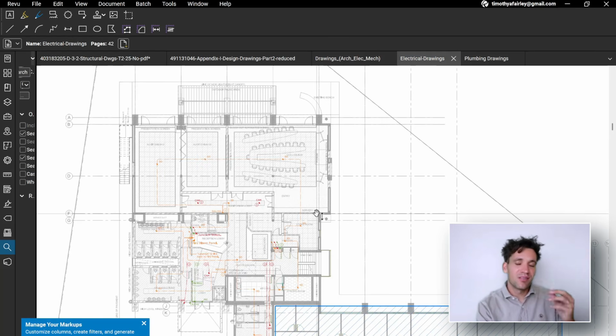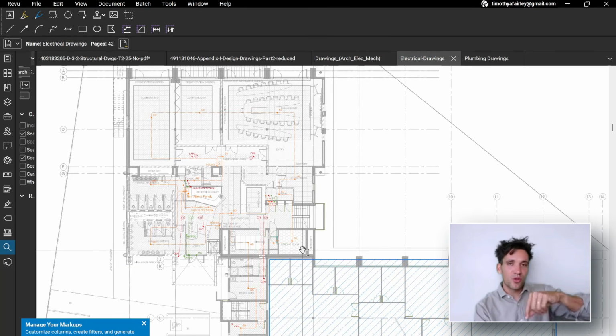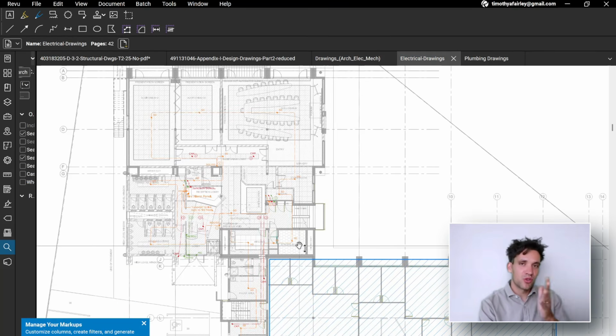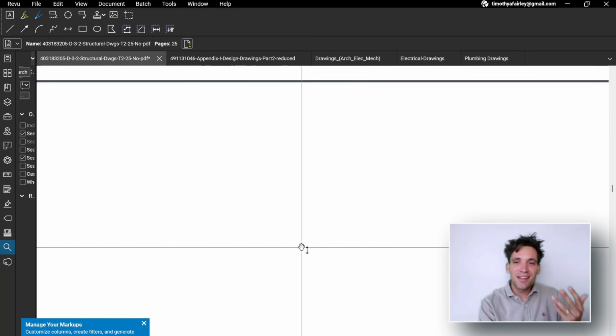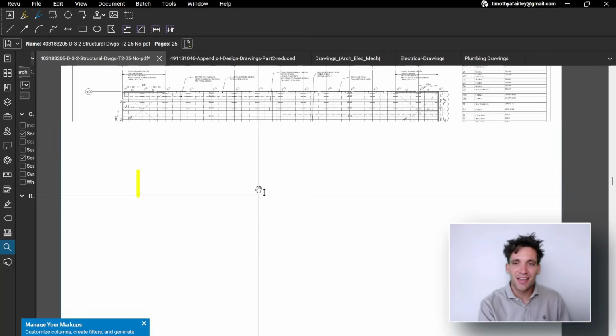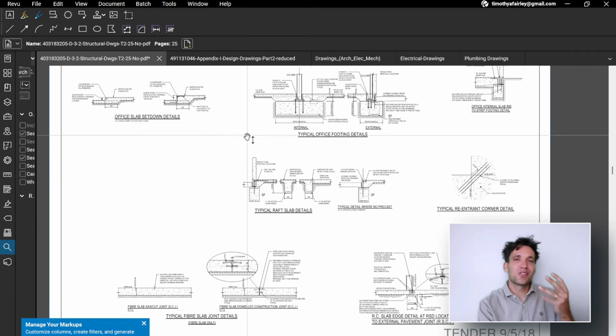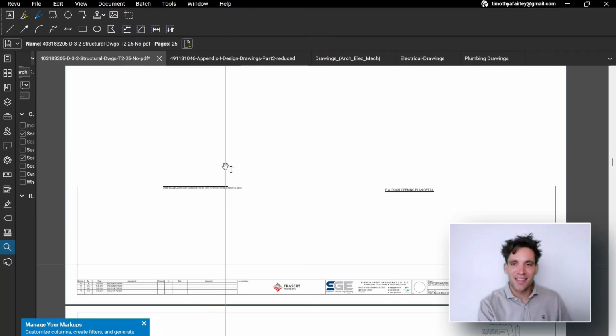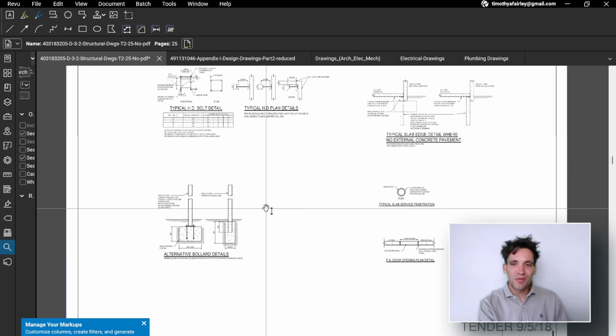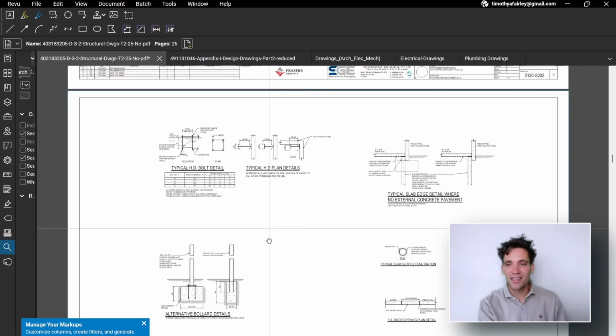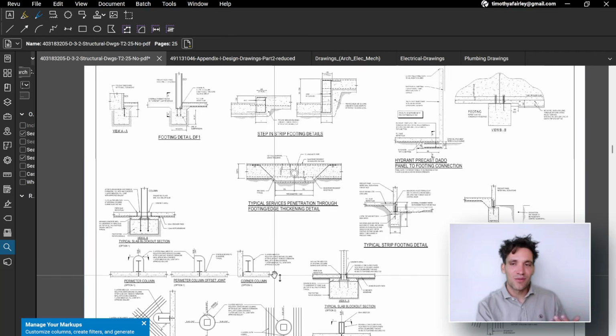We've understood the layout drawings, both looking vertical and then the elevation views from looking across. Once we understand this, we understand clearly how everything fits together. Only then do we start looking at the section views. I can guarantee if you start trying to go through and understand the section views before you've developed this understanding of how all the drawings fit together, you're just going to unnecessarily confuse yourself.